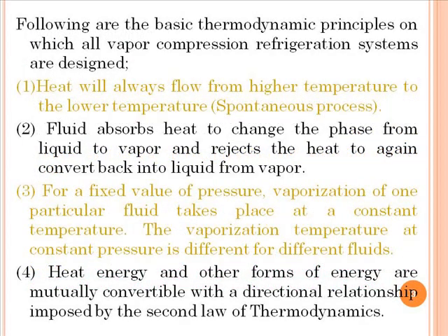Based on the following thermodynamic principles, the VCR cycle is designed. First, heat will always flow from higher temperature to lower temperature, that is called spontaneous process. Second, the fluid absorbs the heat to change the phase from liquid to vapor and it rejects the heat to again convert back into the liquid from vapor.